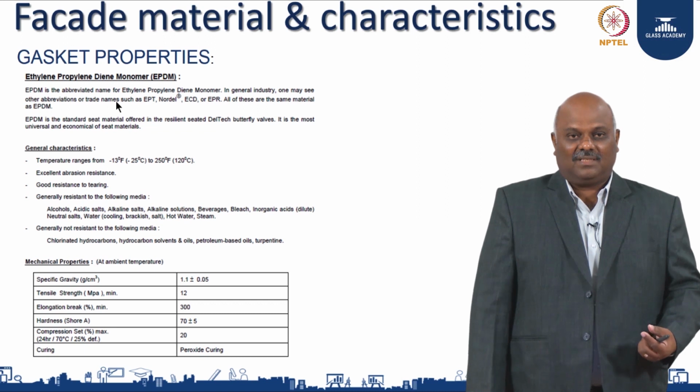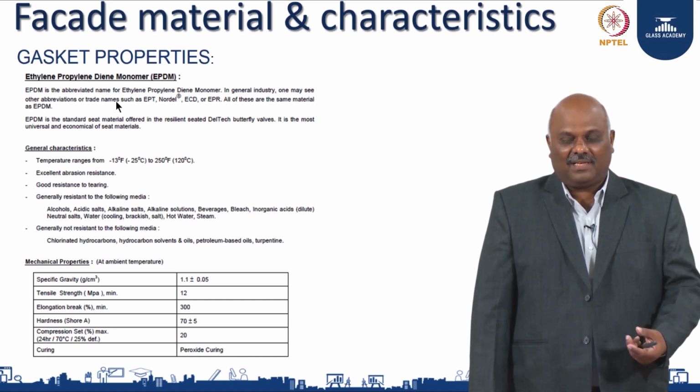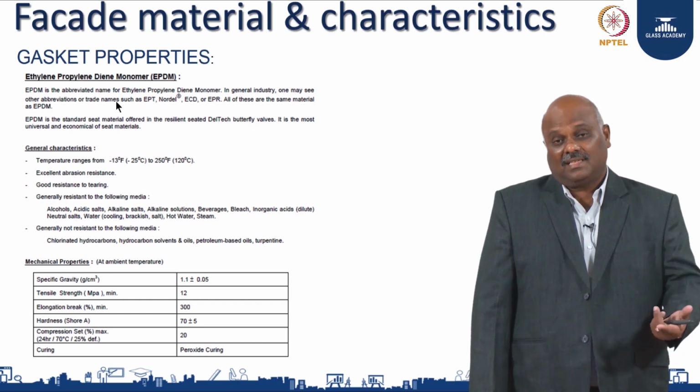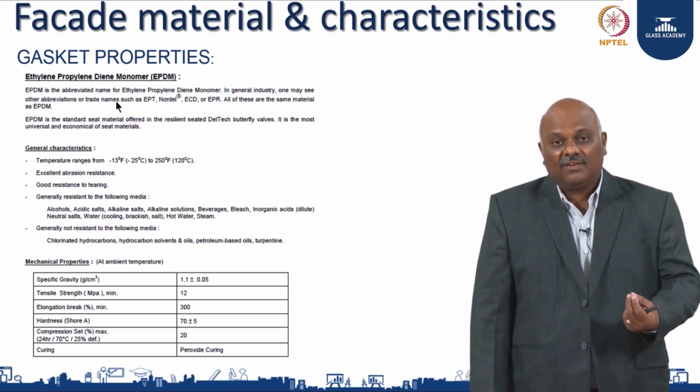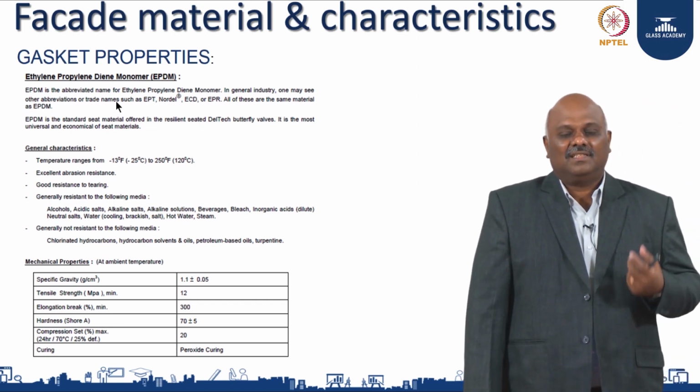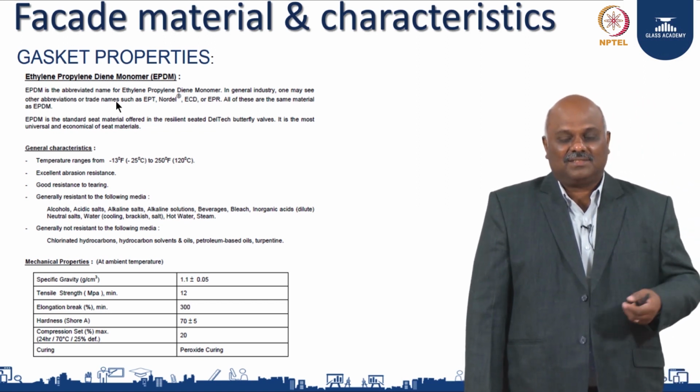You can't put a too hard gasket into a cavity where there is a lot of expansion, then if there is a glass against it, the glass will tend to break. So, you need to have flexibility as well. So, designing a gasket plays a very important factor in the system.